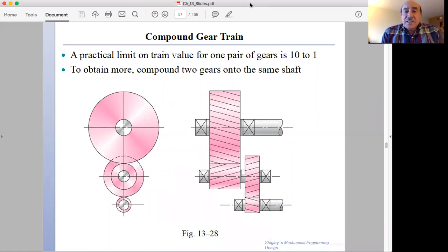as you see here. So in this example, we have a compound gear train. We have an input RPM, an output RPM. So we have a gear ratio. If it is greater than 10, we have to break it up into pieces and then start designing. Typically, you can make it as many stages as you want if we have the time. But typically for the exam, it's not going to be more than 2 stages. So we have a stage 1 and stage 2. We can either have a speed reducer or a speed increaser, and that depends on the input to the output RPM.